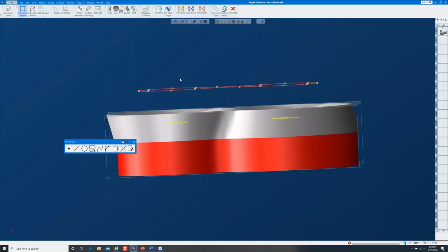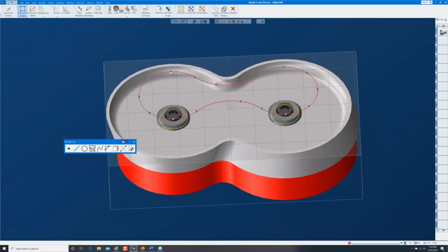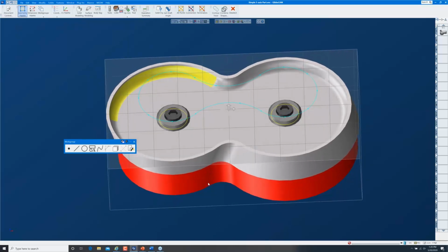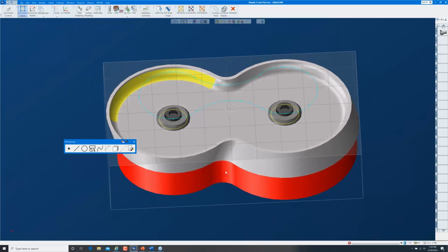And then I can kind of test that briefly or quickly just by rolling this thing around and kind of lining this up with the matching portion of the surface behind it, and get an idea of how much tilt is going to be required to get the tool there. And that's a good amount of tilt. I'm pleased with that. I'm not risking hitting the back edge of the part with my tool or my holder, and I can easily get to that undercut there.